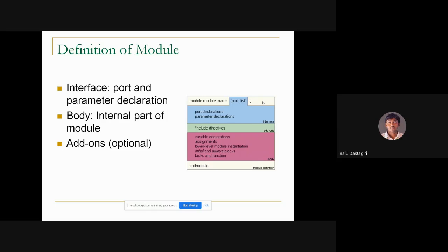You can first specify the inputs and then the outputs, or the outputs and then the inputs, but don't jumble them. But for the predefined gates, the primitives I mentioned, the first thing should be the outputs, followed by the inputs.